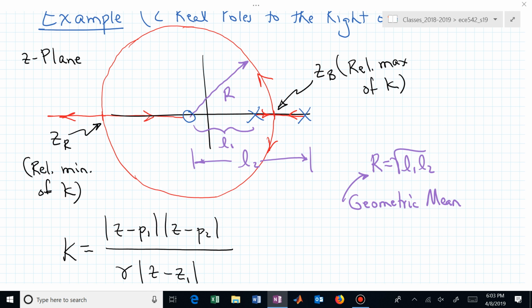We crank up the gain to 2.7. Now we've become complex closed loop poles. We've moved off the real axis. Now we crank up the gain, that knob, and we crank it up to 16.7. Now we're at the re-entry.